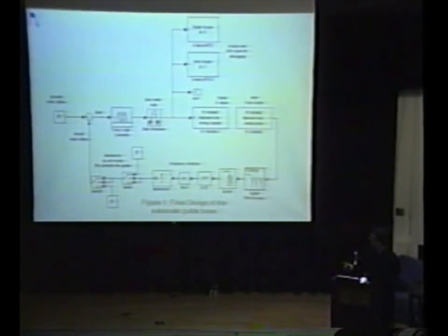It runs an FFT in the absolute value. This is to do a frequency analysis of the note. I'm then able to find the maximum value, which frequency has the most, to find the strongest frequency of the signal. Because I filtered out all other frequencies, the only frequency that will go through is the fundamental frequency and any noise around that note.